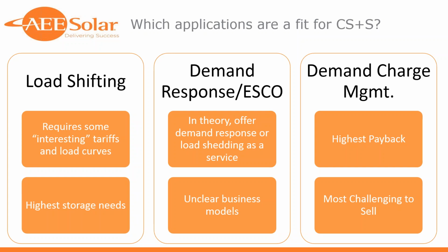However, looking at your bill for 30 seconds, half your bill is demand charges, and this may or may not solve that issue. If you don't know when during the day your demand charges are occurring, a possible really bad outcome would be you install a great, shiny rooftop grid-tied solar system, and you really don't address the demand pain, and the savings are not what you've estimated, and you've got some really unhappy customers.